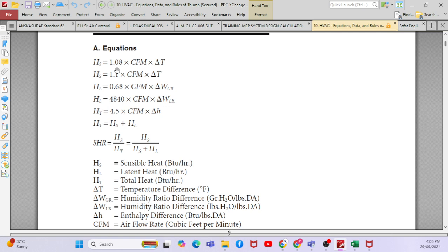Assume that you have 7 degrees, but it should be 7 degrees, but it will go at like 10 degrees or 11 degrees, something like that, because of the bypass factor. So I will explain how to calculate the bypass factor. I have some video as well. I will be sharing the video with you, and we will discuss the bypass factor and everything. Okay, sure. You're clear, right? Yeah.